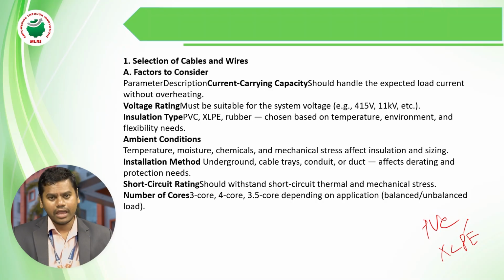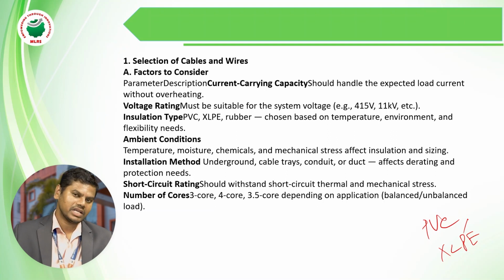After ambient conditions, next is installation method. How to select the cable in installation methods: underground, in cable tray, and conduit or duct, which affect derating and protection needs. These are the installation methods.